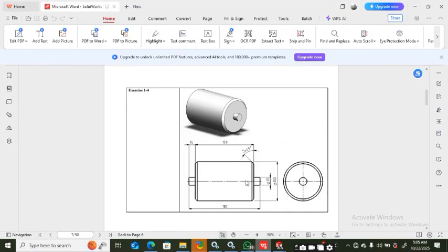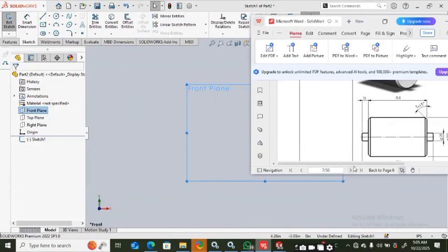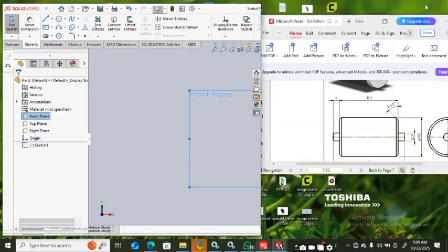And remember from our previous episode, that should be episode 2, in order to achieve the technical approach, we're going to use the item in SolidWorks called the revolve. And in the revolve, before you do revolve, in the sketch property, you're going to design the model halfway, and then you put a construction line in between, and then you revolve in this direction. So we're going to do that right now. Now I'm going to make sure that I share this screen so that it's going to be more convenient for me to use. So I'm going to share this screen as well.